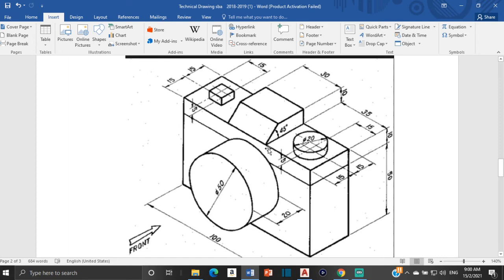If I was to draw a 45-degree angle, it wouldn't properly bisect the angle between 30 and 90 degrees, because 90 minus 45 is 45, and then 45 minus 30 is 15. So this line needs to be exactly in the middle. So in the drawing, when I did it in isometric, this line was drawn at 60 degrees.